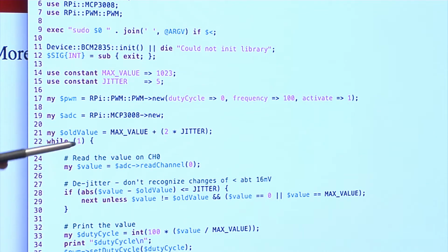The rest of this is looking out for jitter. If you just sat there and watched the values, they'd change by themselves. You bumped the table or just looked at it funny, the values would change. What I'm doing here basically is effectively removing bits from the A2D converter, giving it lower resolution.